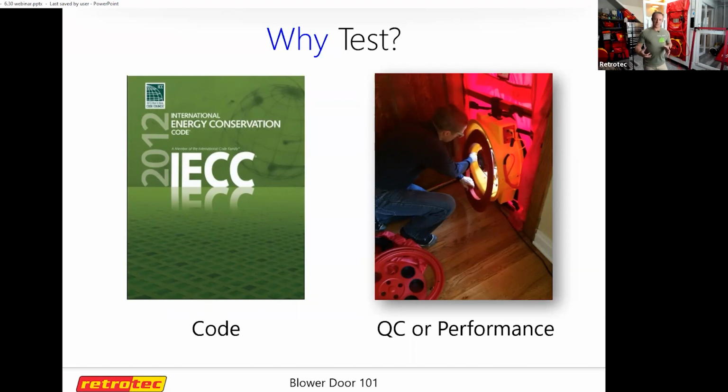Is that going to be controllable for comfort or not? Some HVAC companies have gotten into building envelope air sealing. Some of them work with an insulator that might do that. Or they might simply say, hey, this isn't really an HVAC problem. The mechanical systems look good. This is more of a building envelope problem. So running an air tightness test can help them determine if it's HVAC related or building related, or maybe a mixture of the two.